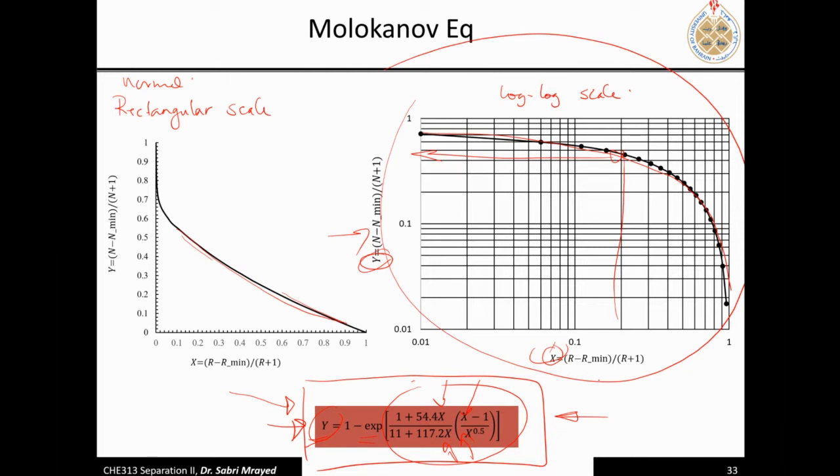So if you're going to use this graph here, you take the x's, of course, at certain reflux ratio. Okay, you come to get x, and you're supposed to have R minimum, as we said, because we know R minimum, given information, and N minimum, and I have what is the value of N at R. So you know R minimum and N minimum. You come to this one, you get x, let's say it was 0.1 or whatever, you go up here, and you get your y immediately.